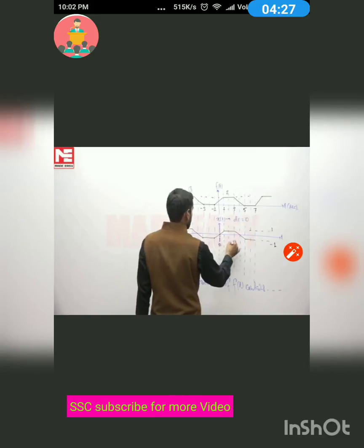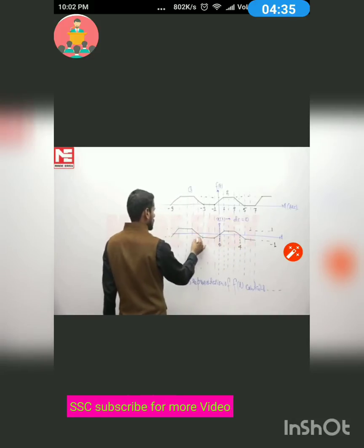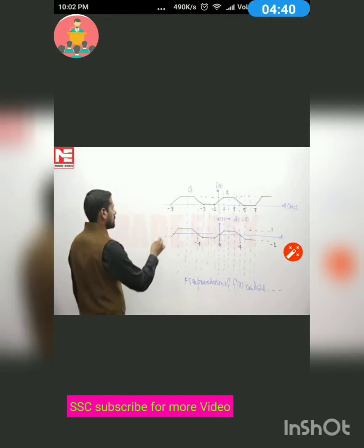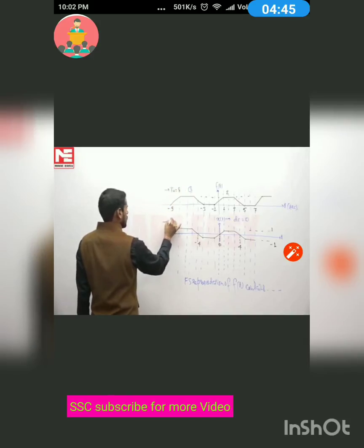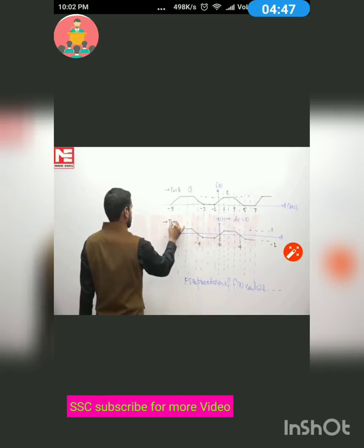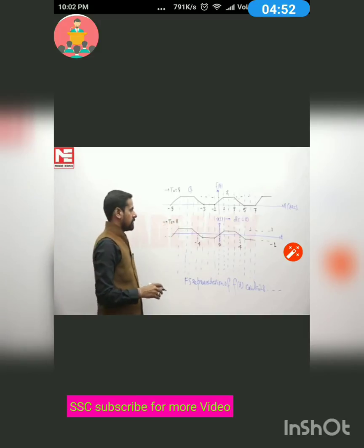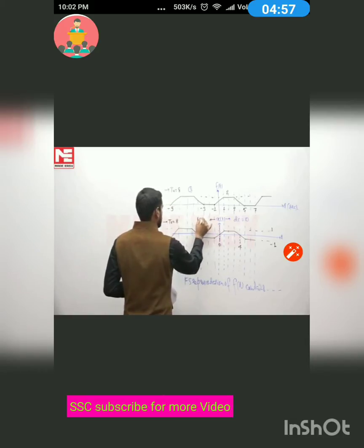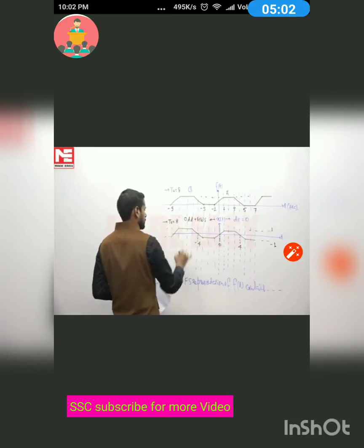This time instant is 0, this time instant is 4 and this time instant will be -4. Therefore, the time period of the given signal is 8. The time period of the signal which I have drawn is also 8. If we check, this signal x(t) satisfies half wave symmetry, and the given signal is odd also.